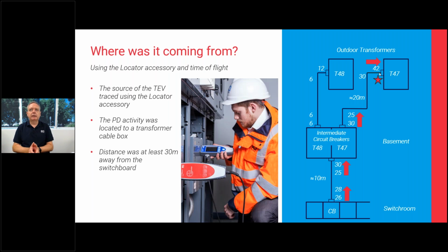So what we actually did in this instance is we found that the discharge was happening and the repair was not optimal, or had not had the desired effect of removing the defects, and this secondary defect was then planned in for replacement, doing things in a much more planned and orderly manner during the next outage, which was coming up at Christmas time. That was done, and the second failure was prevented. So just because we're getting things in the circuit breaker, we do have to do that little bit of investigation to see where things are coming from.